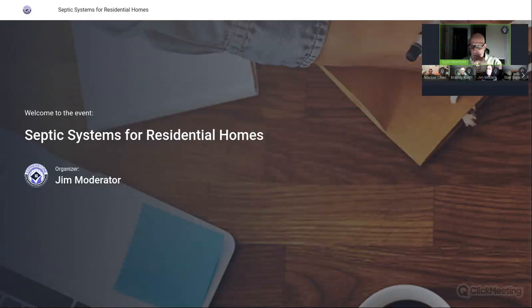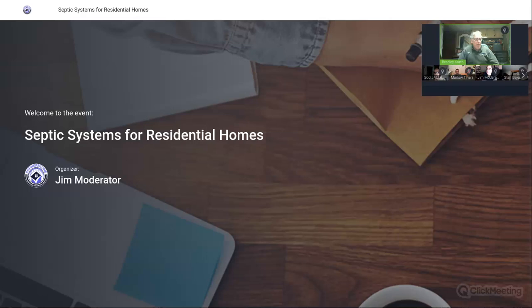One other thing I was going to ask, Brad, and I can't remember. What's the distance? You might have said it, and if I did, I apologize. What's the distance from a well? Did you talk about the distances from a well? Yeah, it's in the presentation, and it depends on the required flow rate from the well. But for most residential, it's going to be 75 feet to be code compliant.